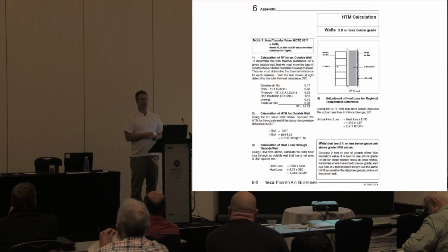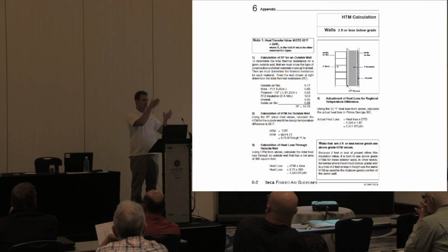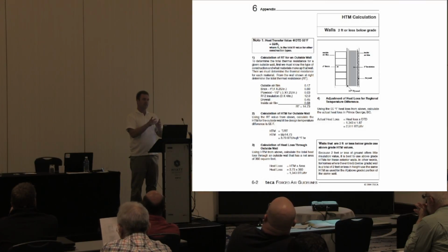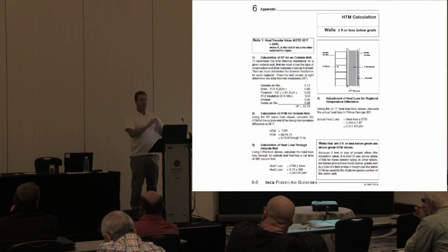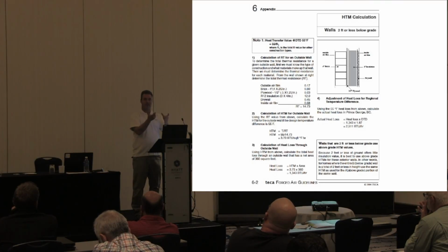So we took some pictures, and what ended up happening was a big chunk of the room was missing, not like the whole wall, but there were lines of warm coming through the wall that you could see, not just that stud line. If you guys have ever seen those pictures, when they take a picture of your house, if it's really concentrated, you can kind of see where the stud line is because it doesn't stop the conduction of the heat as much as a bat does, but it's still not smoking hot.